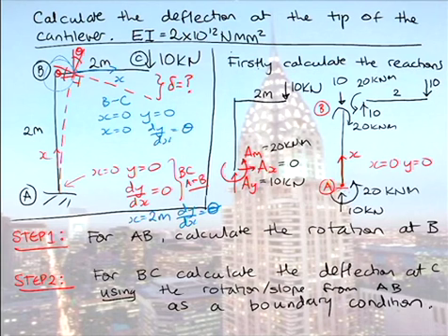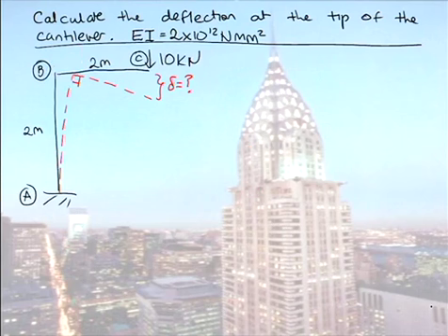This is pretty full on. I'll admit it's pretty full on. Okay, so we've got our two free body diagrams. When you deal with free body diagrams, it doesn't matter. So now I'm going to step A. I'm going to look at my boundary condition, my free body diagram AB. So looking at AB, we said there was a 10 down, which causes no deflection. And we said there was a moment here of 20 kilonewton metres. Now that still looks damn ugly.